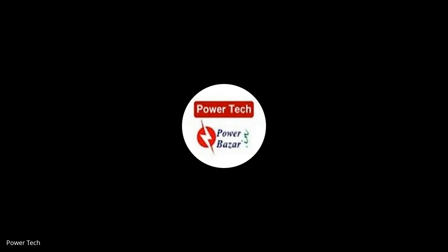4-quadrant reactive power. That is again whether you are importing or exporting, in all the quadrants, there is a reactive power. Whatever import is there, that has to be taken care of. Whatever quadrant, you have to have your own reactive power installation and you should meet it. If you are not able to meet, then it is again chargeable only, or it is punishable.